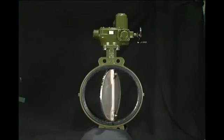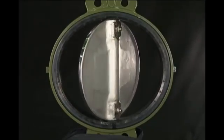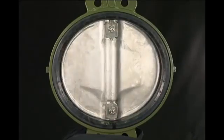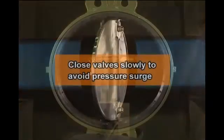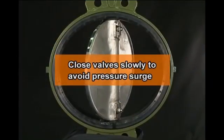Pressure surge is a factor of possible danger with valve opening and closing. It takes place when the flow velocity suddenly changes inside the pipeline, filled with fast-flowing water, due to abrupt opening or closing, whether remote or manual, of butterfly valves. In the event of a pressure surge, a high-pressure face propagates through the pipeline at a velocity faster than the speed of sound, causing damage to structural parts of the pipeline. So valves must be opened or closed slowly.